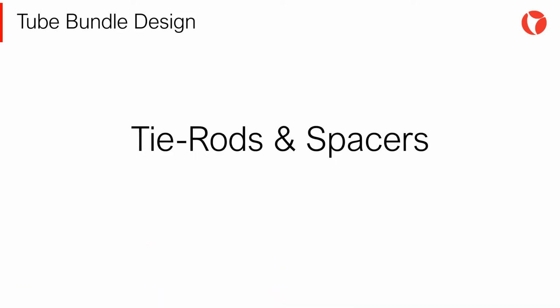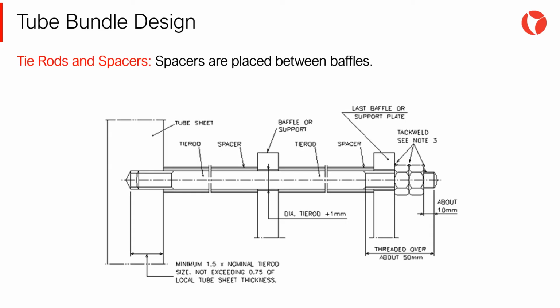Tie rods and spacers keep all the elements of the bundle as one piece. The function of tie rods and spacers is to create a rigid structure between the tube sheet, the baffles, and the tubes, constituting the tube bundle as a single item. For removable tube bundles, one end of the tie rod is anchored to the fixed or stationary tube sheet. The required number of tie rods and their size is a function of the shell diameter and should be distributed evenly throughout the outside edge of the tube sheet.